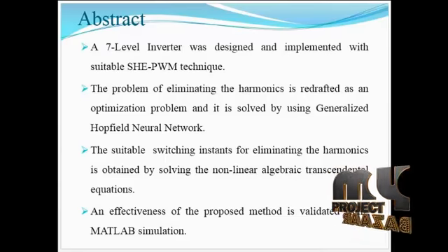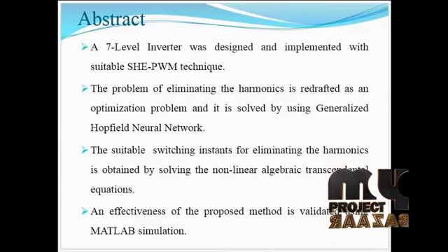This paper presents two techniques for improving the quality of output voltage and efficiency. That is, the real-time implementation of PWM, the selective harmonic elimination pulse width modulation technique in a single phase inverter, is proposed. The disadvantages of this paper are that the level of output voltage depends upon the number of DC sources, and several carrier signals are used. Also, the third and fifth harmonics have been eliminated, but the higher order harmonics 11 and 13 still disturb the output voltage waveform.